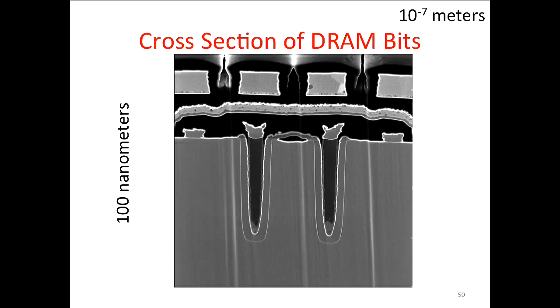It turns out that depends on the temperature, and it takes a lot of power to refresh it like that. So in mobile phones, you actually have a temperature sensor, so they know how hot it is. The hotter it is, the more leakage there is, because the electrons have more energy, they can move more easily. And so on your phone, it'll actually have a temperature sensor telling the system how often it needs to refresh. The idea is when your phone is cold, it doesn't have to refresh as often, and so they can save power. And when it's hot or it's in your pocket, it's actually going to refresh more often, right? So it'll take more power.